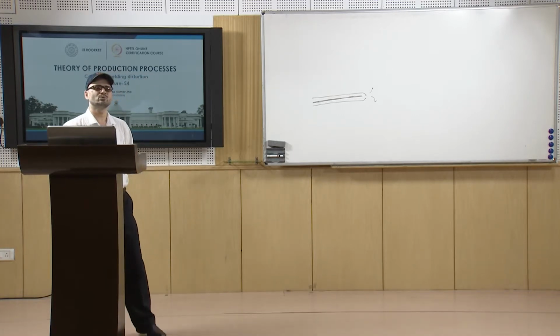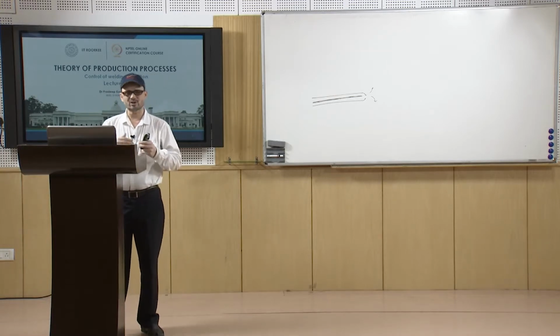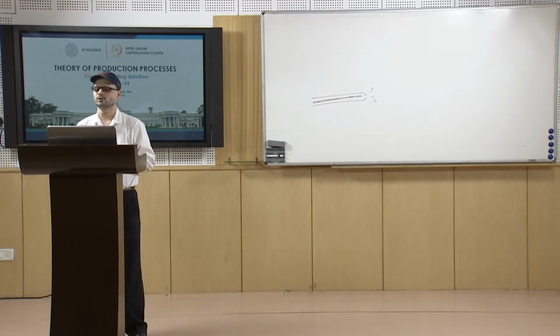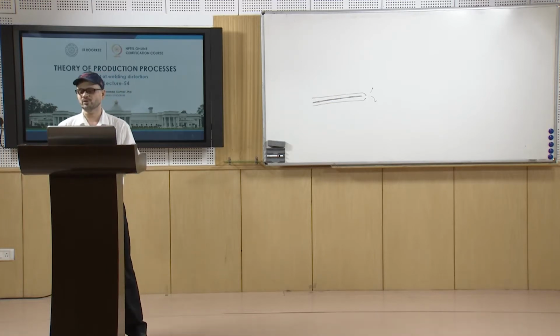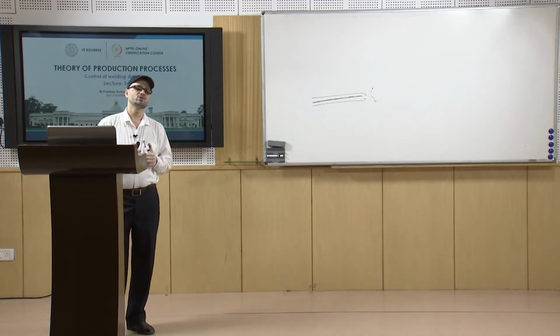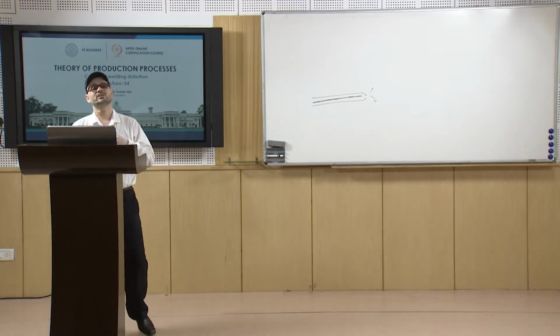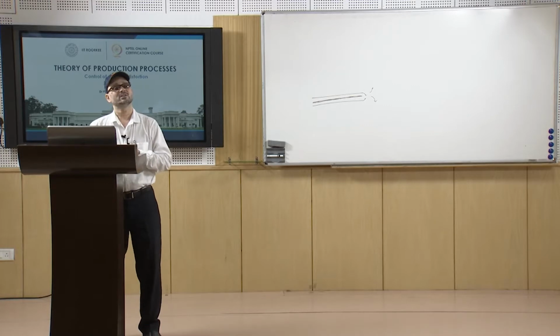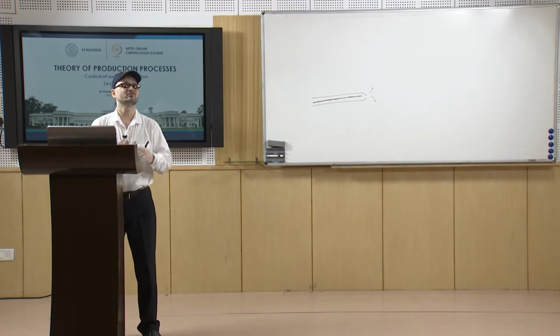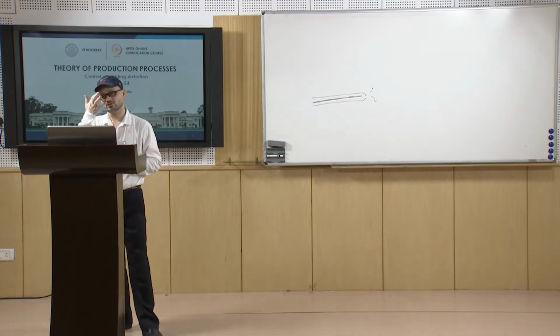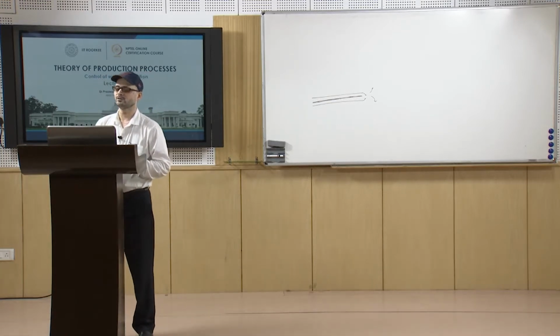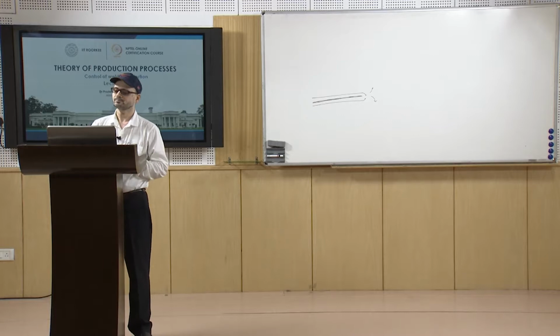So, what we normally do is preheat the material before tacking. We preheat the plates, so that when we tack, the heat extraction rate will not be that fast, and it will avoid any kind of hardness or cracking during that process.